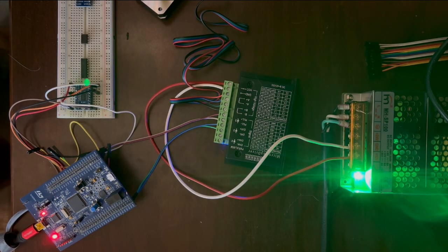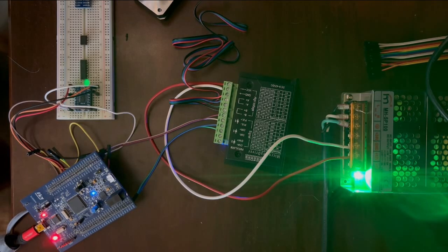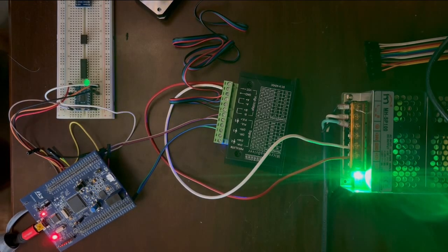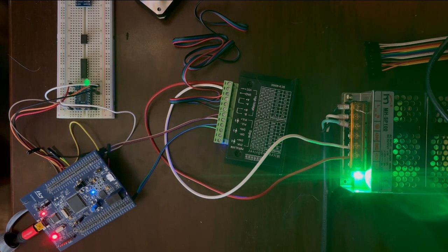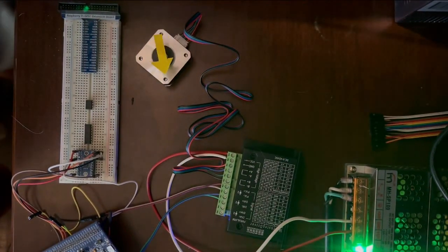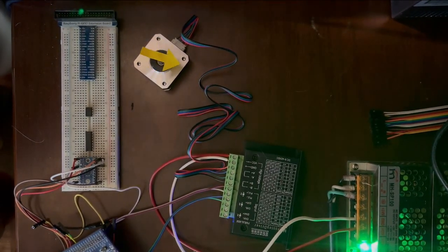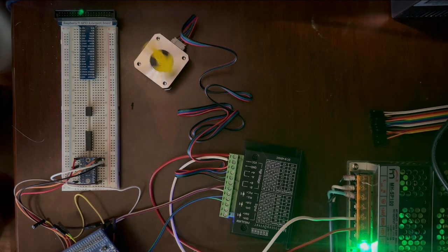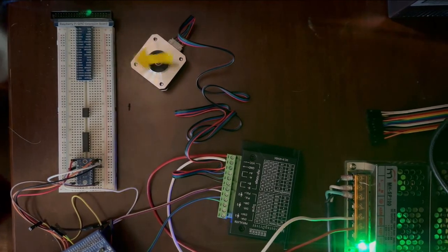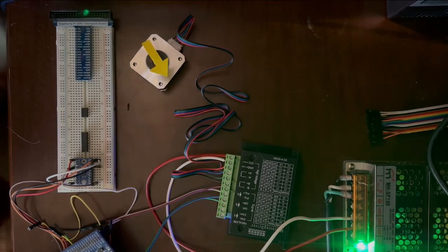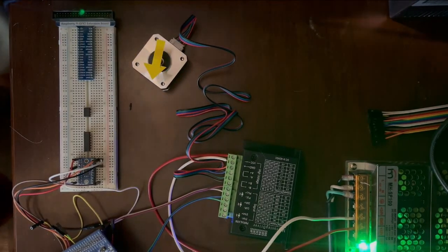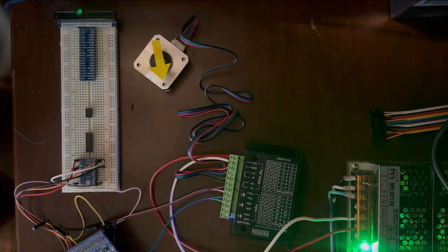The speed is a little more difficult to calculate, because it depends on the base time unit of our timer, which is going to be impacted by the ARR, the prescaler, and the clock on that timer bus. So let's go through and write this code as an example. It's just one example of how we can program stepper motors. Obviously there are many ways to do this. This is just one way to go through the calculations, and I think it's pretty helpful to show how we can write a function to accomplish this.